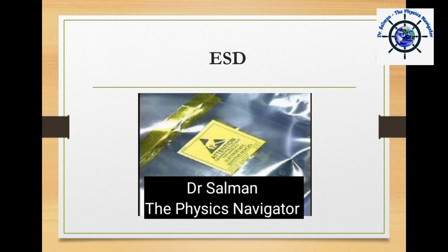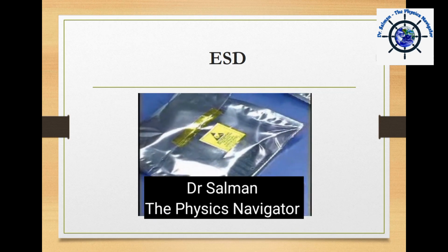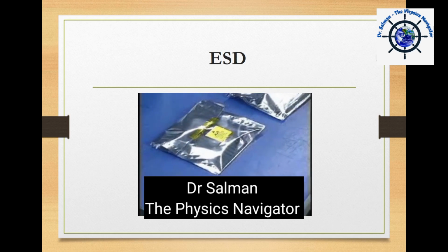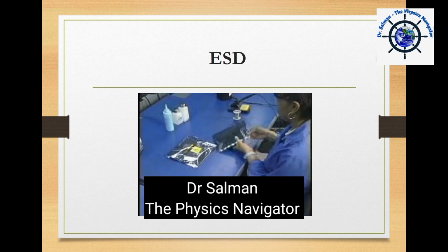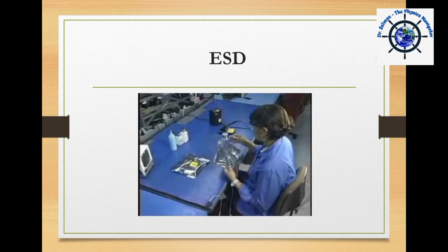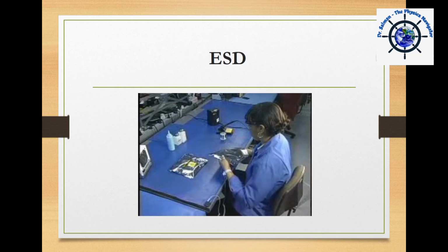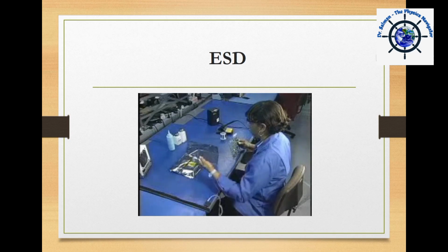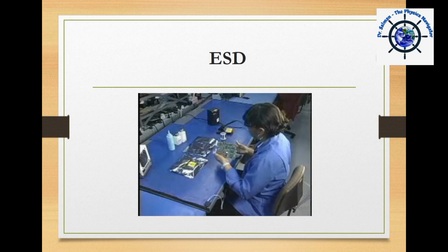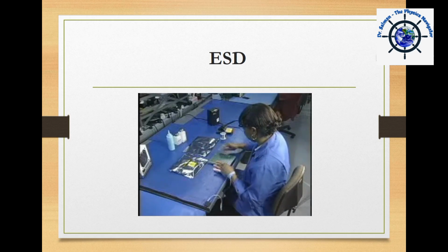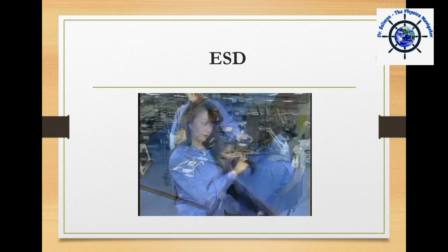We've just looked at a number of ways to control ESD in our work area. ESD control works most effectively when you assume that all the components and assemblies that you handle are ESD sensitive, even when they're not. ESD sensitive devices should be properly labeled, but sometimes someone forgets. That's why it's important to get in the habit of performing all activities with ESD safe practices.